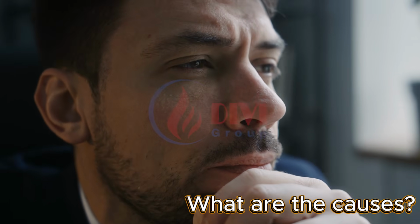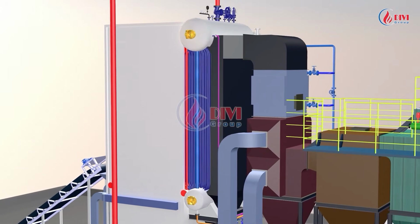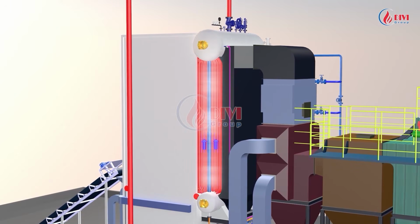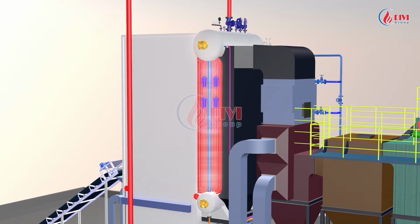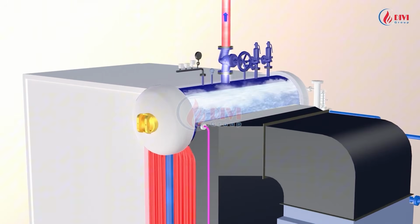So what are the specific causes? Let's take a closer look at each factor. Because number one, this is a typical design of a two-drum water tube boiler. The lower drum holds water, the upper drum holds both water and steam. Evaporation takes place in this upper drum. At the same time, feedwater is supplied here.